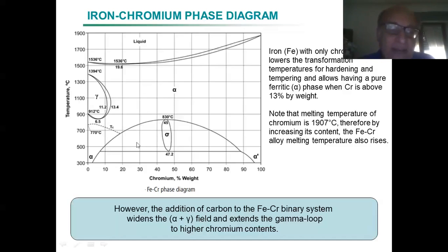As a matter of fact, having 27% of chromium, as in one of the steel categories like the 1.4444, it becomes a bit too close to the presence of the intermetallic. Apart from that, I will come back to that later.